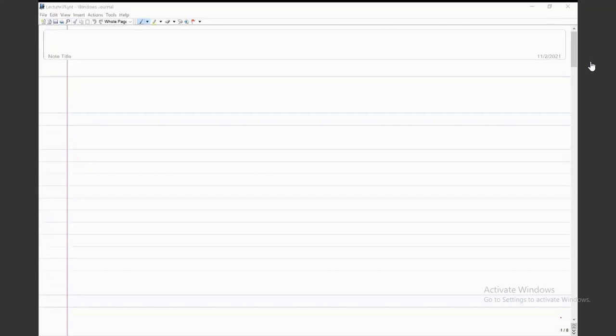Actually, I was thinking about U3 as the net displacement from the reference. Yes, U3 is the net displacement from the reference only, from the initial position. Okay, sir, I got it. So when the gap is closed and further deformation is happening, U3 minus U4 will be equal to G. That will continue to remain as G. Okay, sir. Thank you, sir.